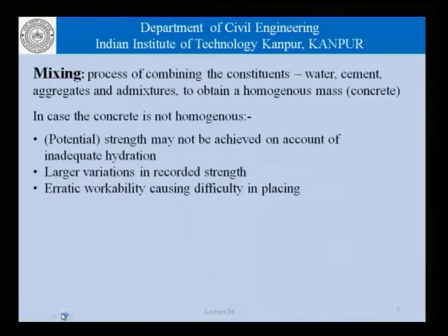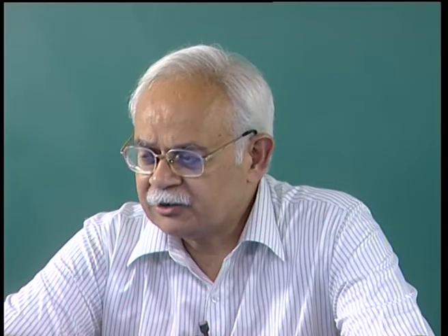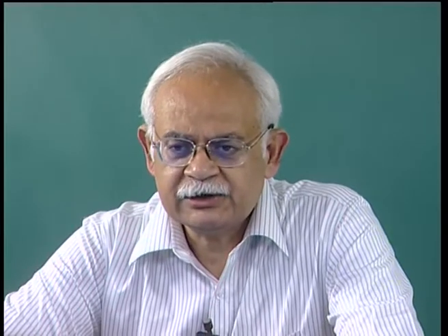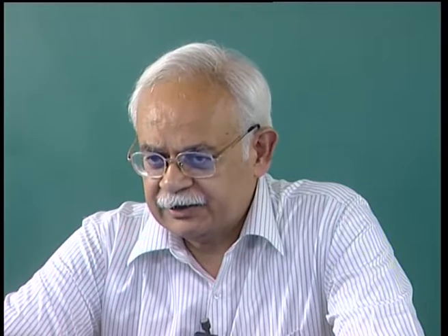Now, in case the concrete is not homogeneous, the potential strength may not be achieved on account of inadequate hydration. We are talking of potential strength here, because when we mix the concrete and allow it to hydrate with curing and so on, there is a strength that it can achieve, beyond which a particular mix, depending on its proportions, will not gain strength.